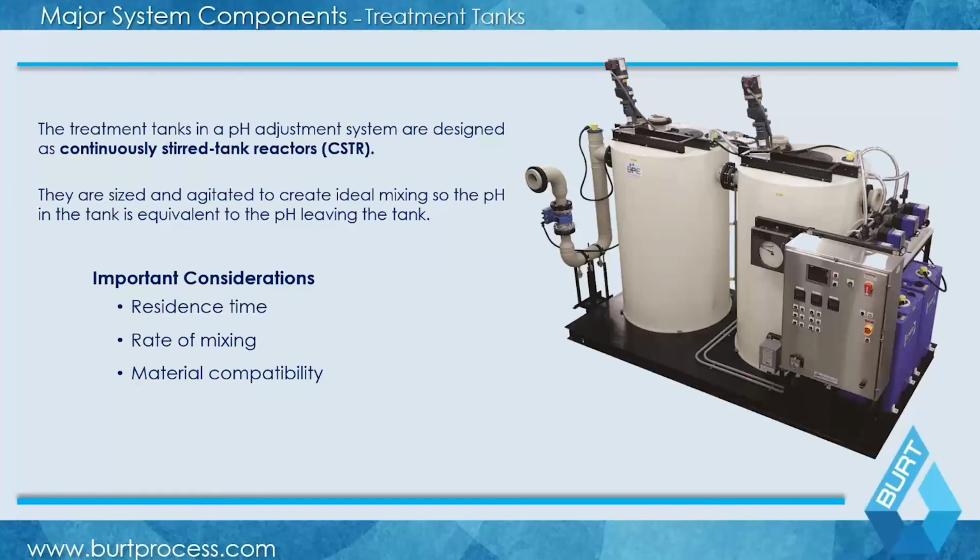All pH neutralization tanks operate as what's referred to as a CSTR, continuously stirred tank reactor. What that means from chemical engineering is within your tank, as waste is coming in, waste is leaving, and your reagents are coming into your system, you're essentially ending up with an ideal solution based on the agitation going on in your system. As a result, in the actual pH tank, you aren't so much treating a flow rate, you're actually treating the volume of the tank in that steady state configuration.